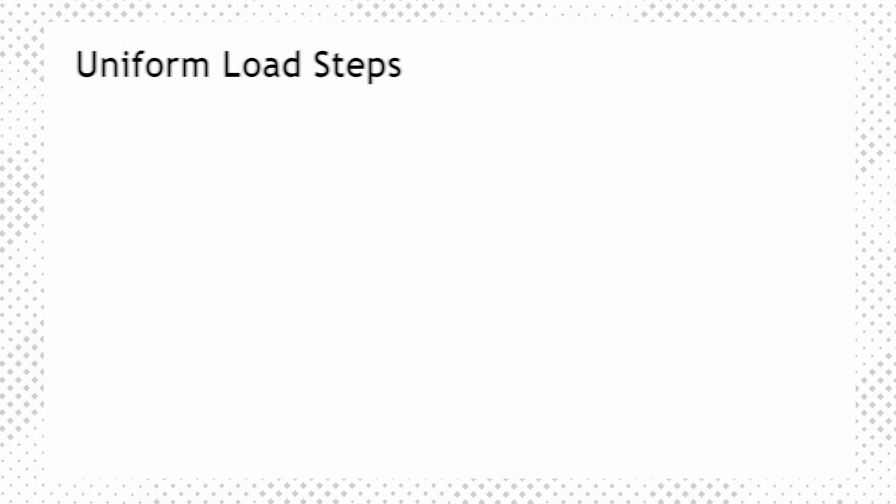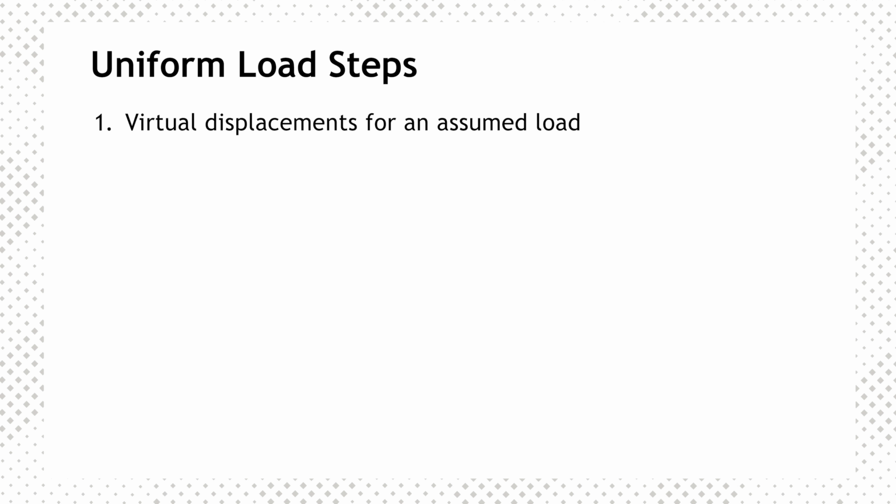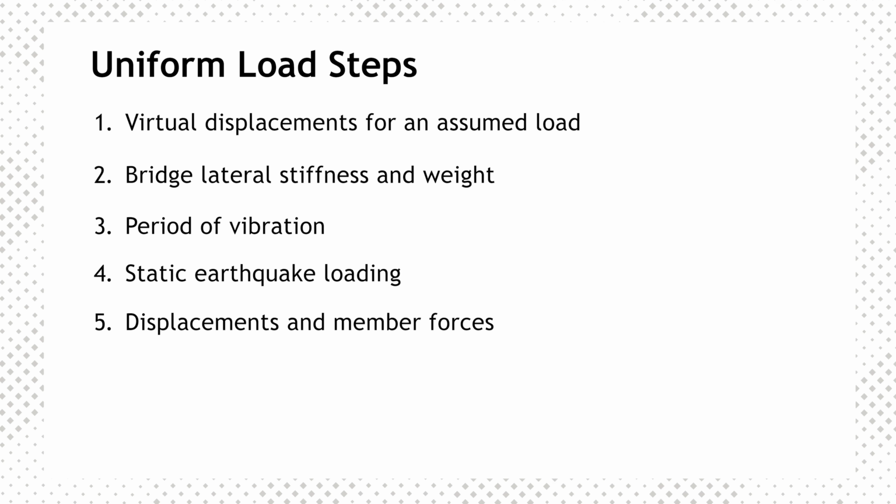Let's look at the uniform load approach of the equivalent static analysis method. We find displacement demand by calculating virtual displacements for an assumed load, bridge lateral stiffness and weight, period of vibration, static earthquake loading, and displacements and member forces. We begin by modeling the bridge in finite element software. While other analytical methods are available, this is the most effective tool.